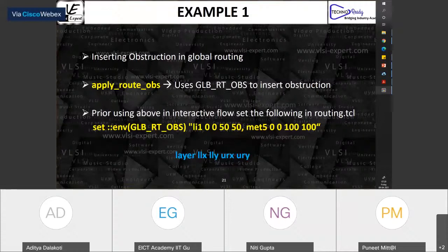Okay, so going from the bottom, the tolerance variable in our config files. Basically, what it means is you've set a target skew, right? So how hard will the tool try to meet that target skew? There might be cases where it is not able to meet it. If you set a big tolerance, then it will try very little to meet that. If you set a very small tolerance value, then it will try very hard. It depends on how much time you want the tool to spend on clock tree synthesis. I want to aim to give you a regression script at the end of today's session as well, where you can set a regression and try that.